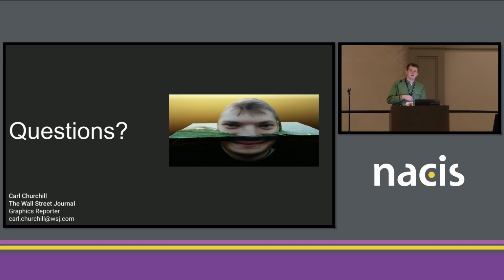So it depends. The quick gist of it is for the DEM, I have an OpenTopography plugin in QGIS that I just zoom in on my canvas, get a NASA DEM, and then you can follow Daniel's tutorial to learn more about the exporting process, and then you can also ask me and I can give you more information about that.